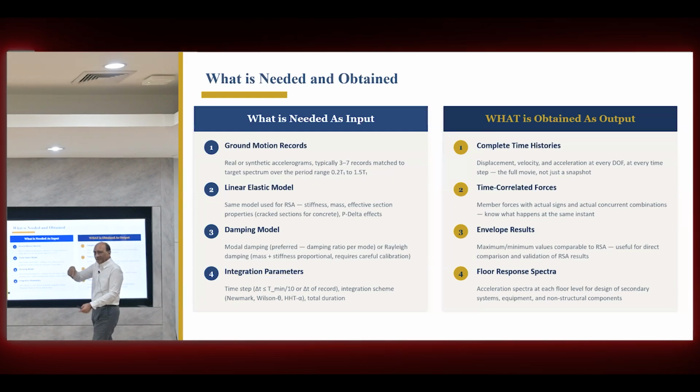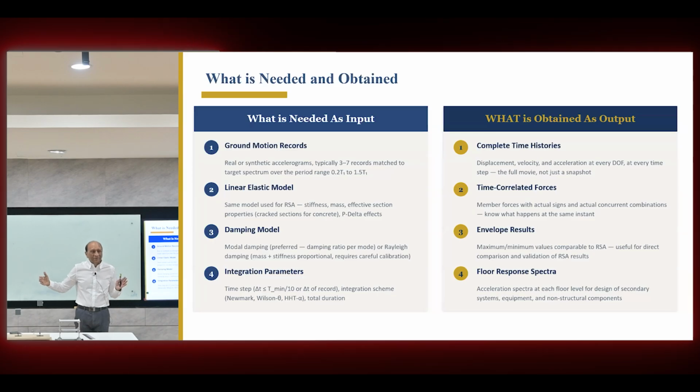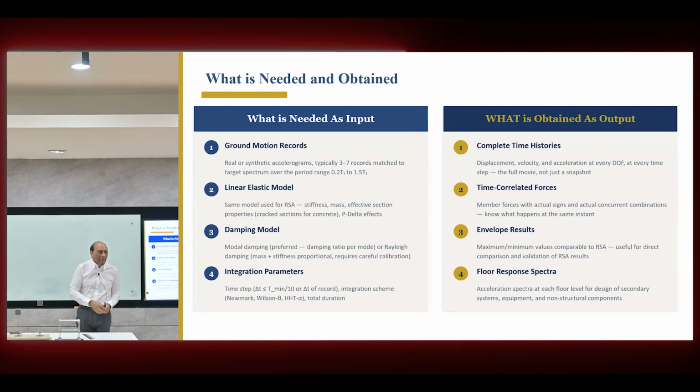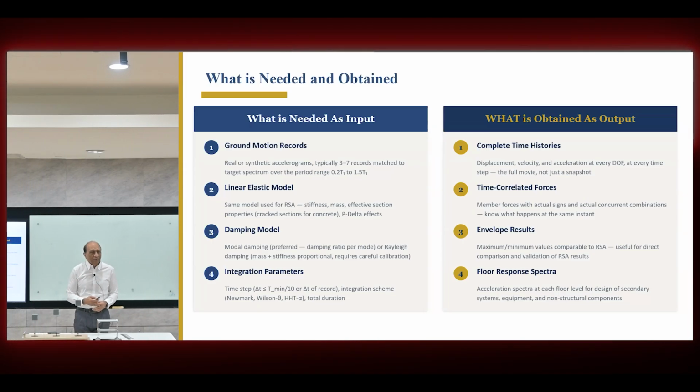So now you know that you can use the envelope for the whole time history rather than using the absolute response that you got from the response spectrum. So that's the advantage of using the linear time history analysis. And we always recommend people just run it anyway because it doesn't cost you much.